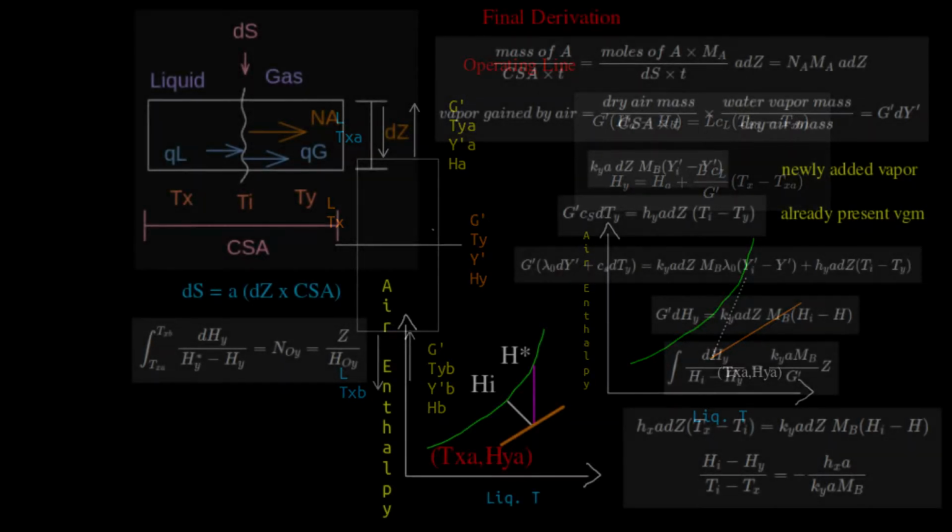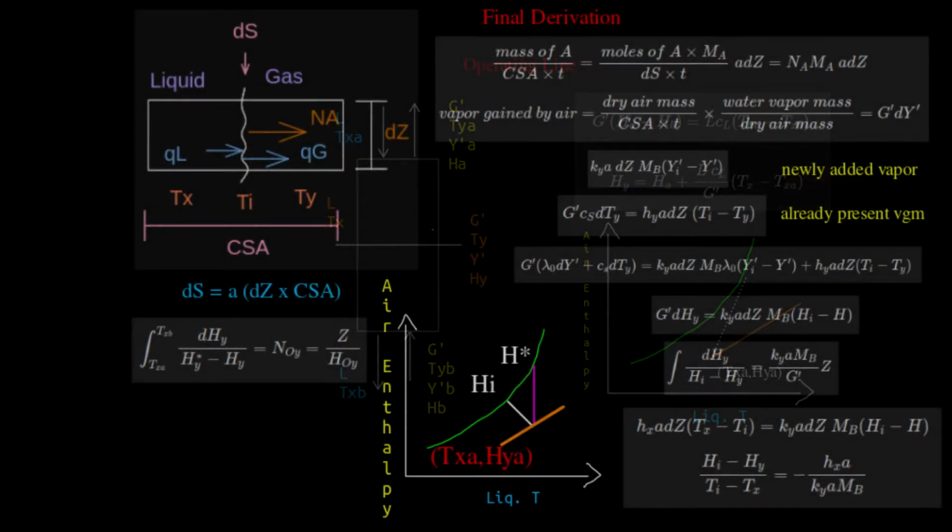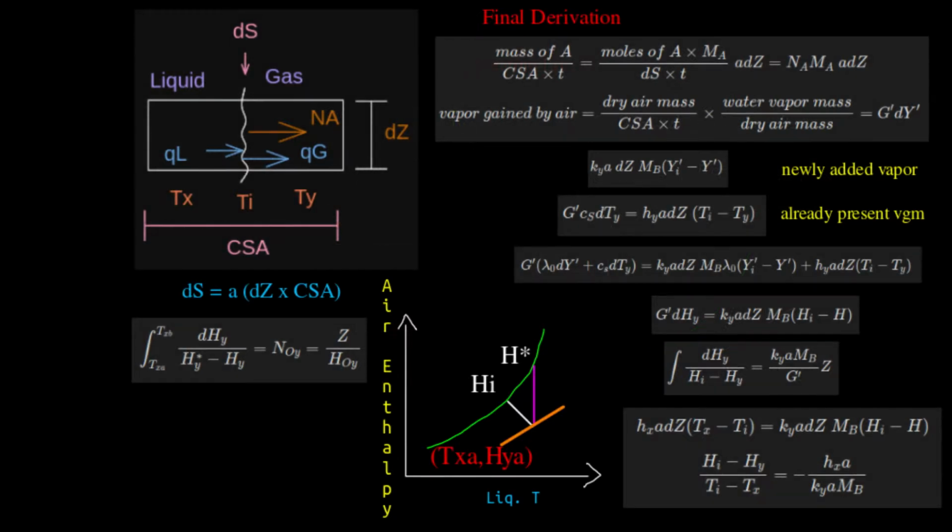So to relate the height with enthalpy, our hero sits down with intense focus and does the analysis. Hours later, our hero goes to the board of directors and says, "We have to integrate the inverse of the vertical distance between the equilibrium and operating enthalpy curves to find the number of transfer units required. Multiplying the number of transfer units with the height of a transfer unit given by the manufacturer will provide us the height of the tower." This is the essence of our analysis.